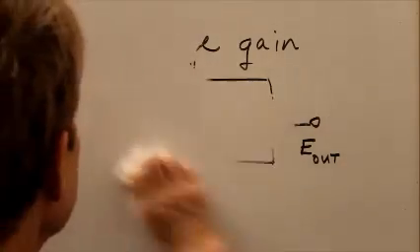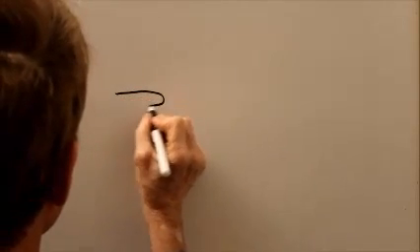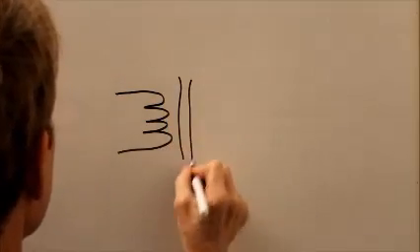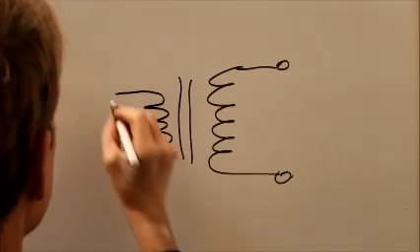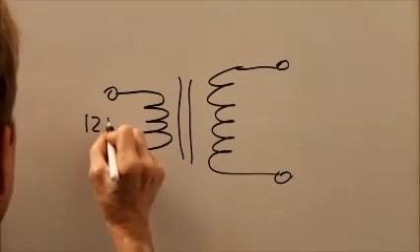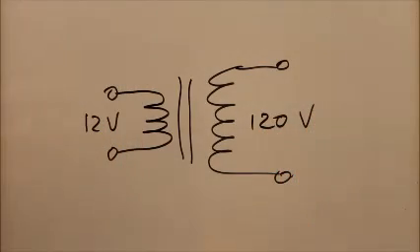Now, there's a reason why we insist upon these impedances having no reactance and in particular having the same resistive value. If we didn't impose that requirement, we could take, say, a step-up transformer, put 12 volts AC into it, get 120 volts out of it, that's 10 times the voltage. We could claim that this transformer produced a 20 decibel gain in terms of voltage.